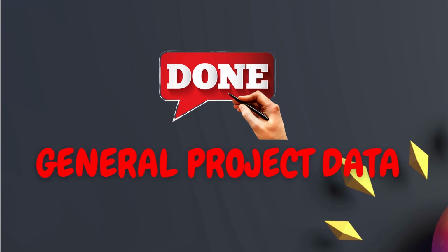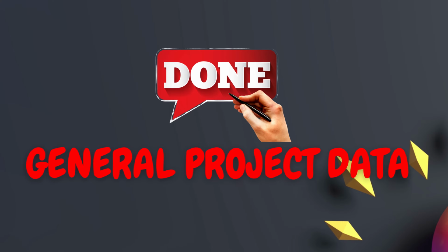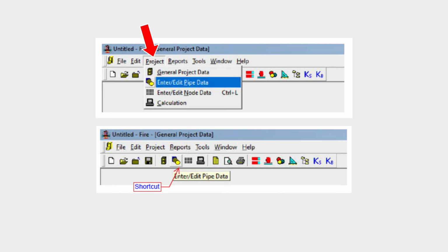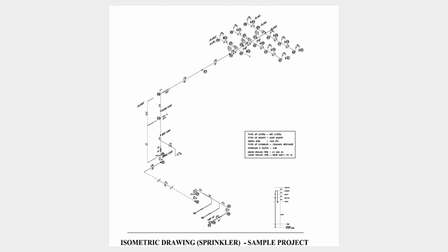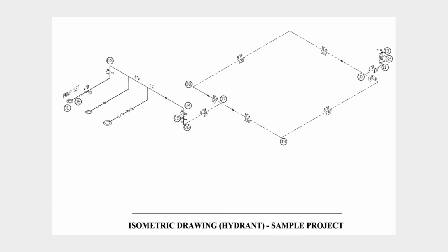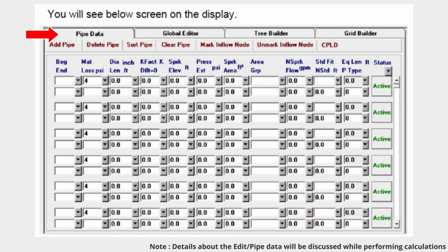We have completed entering the general project data and now it's time to input or edit pipe data based on the isometric diagram prepared considering the most hydraulically remotest design area. Clicking on the pipe data will bring up this screen.